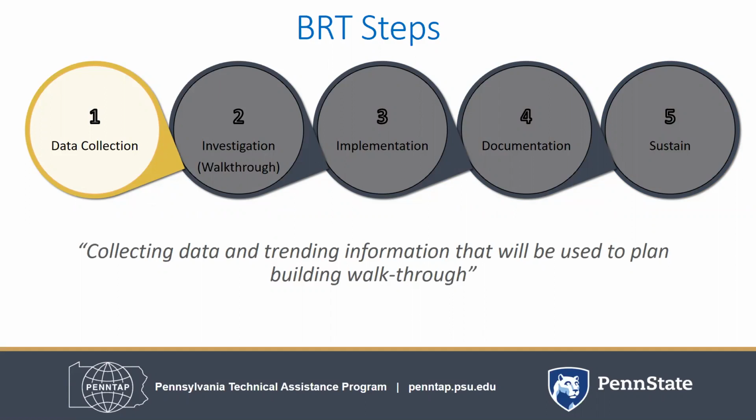Types of data you should consider collecting are meters in your utility bills, the size, age, and type of building, as-built and construction documents, operation and maintenance manuals, sequence of operations, types of equipment, recent repairs, or equipment maintenance schedules, construction or changes to the building, building occupancy, planned shutdown schedules, the original use of the building, and the current mission of the building. After the data is collected, you can start to profile the information you have.